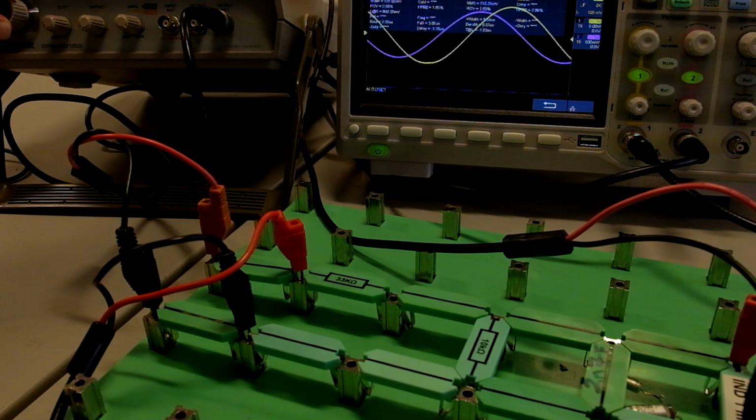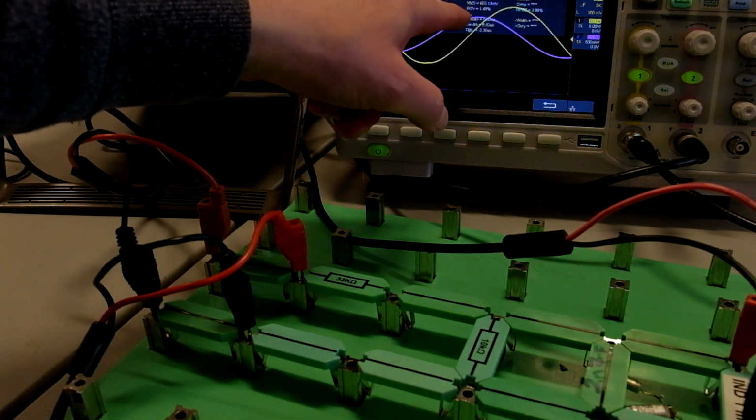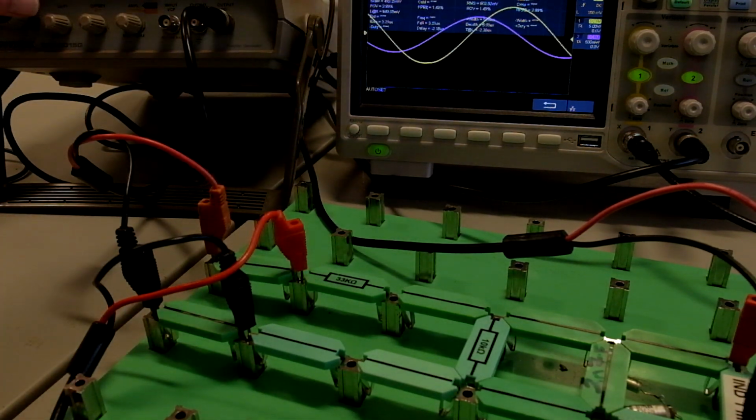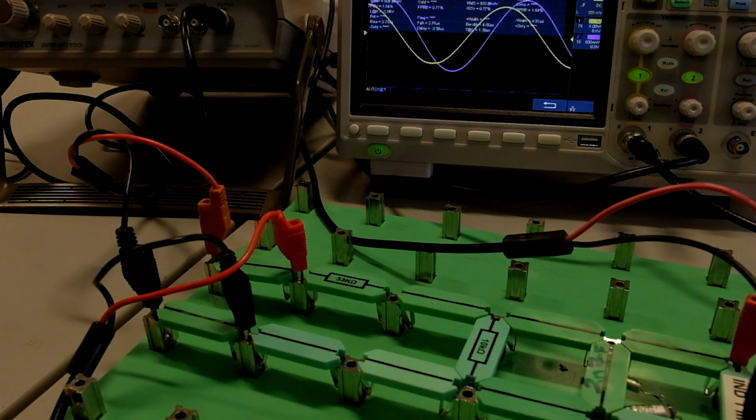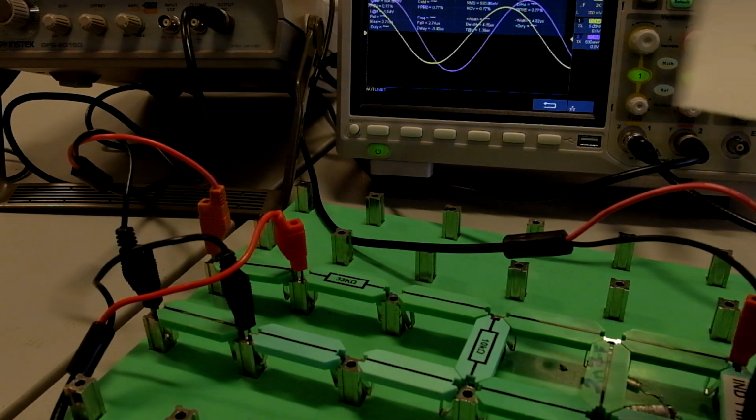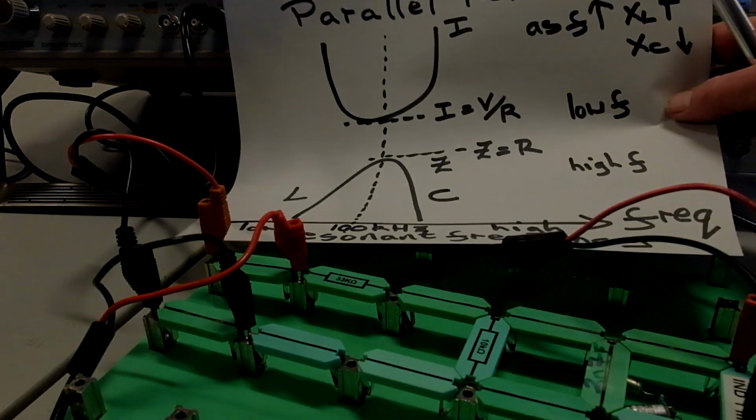So at lower frequencies, the voltage coming out is leading the input, it gets to a peak before V in, so the voltage leads. At the particular resonant frequency, we're completely in phase at 97 kilohertz. If we increase the frequency further, V out reduces, and now V out lags the sine wave going in, which is what we would expect. So what we've got here is a resonant circuit. We've proved the voltage gets to a peak.